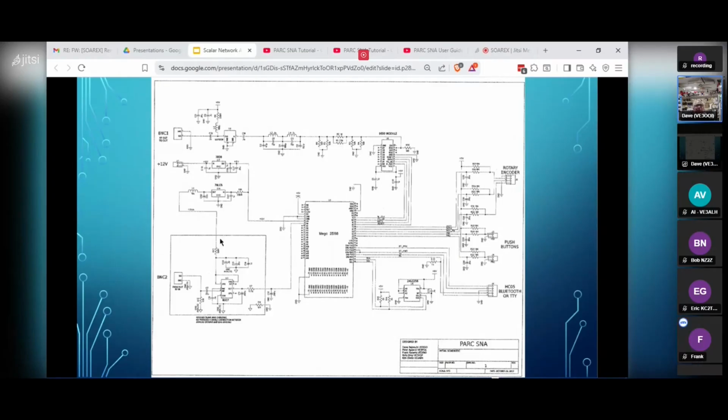So I'm just quickly showing the schematic. I'm not going to go through this, but here's the 8307. You can see it's on an isolated ground plane. There's a 0 ohm resistor connecting the two ground planes together, and everything that feeds into this section has a filter. This one has an LRC filter coming in, and this connection here has an RC filter. So we filter anything going into here to try and reduce the amount of noise that the 8307 would have. So that's it.